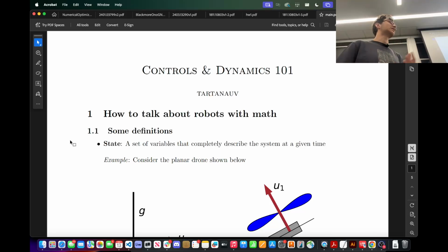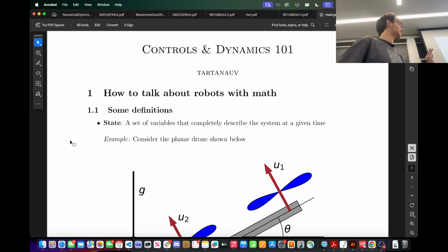And so we ultimately care about using the actuators on the vehicle to do what we want the robot to do. And that will come at the very end of the pipeline after the mapping has done its job, localization has done its job. We know where we are. If you guys went to Theo's session a couple days ago, he spoke about how we know where the robot is. Having an accurate localization stack is incredibly important to do any sort of control, because in the most basic case, if I want to go somewhere, I need to first know where I am to know how far away I am from the place that I actually want to go. So having really accurate localization is very important, and this relies on a lot of other stuff in the stack. I just want to preface with that.